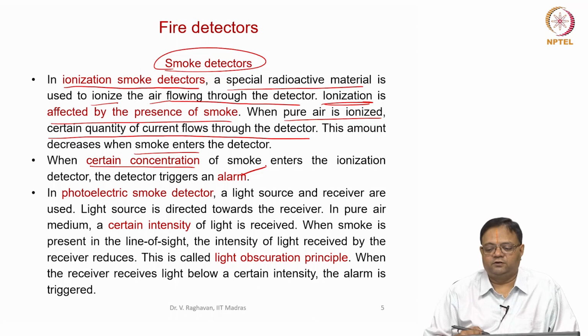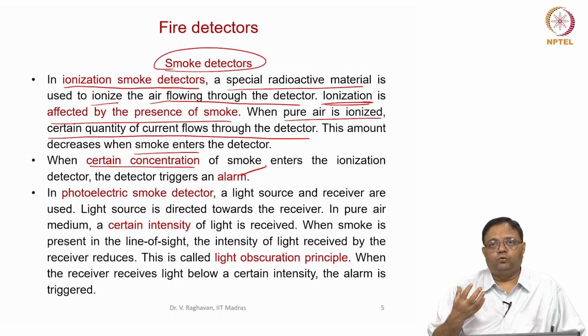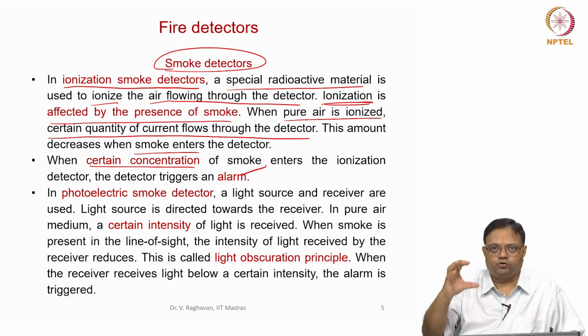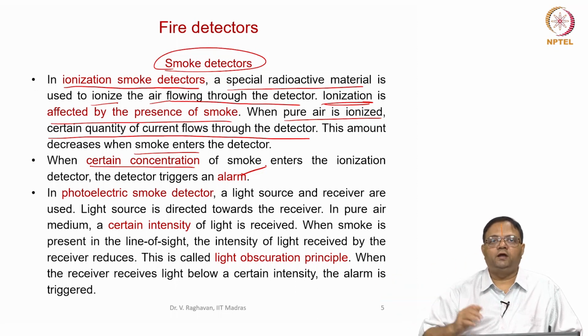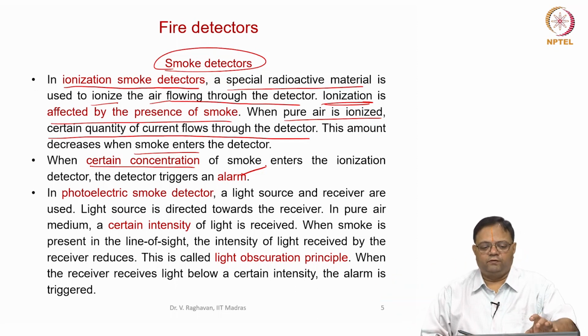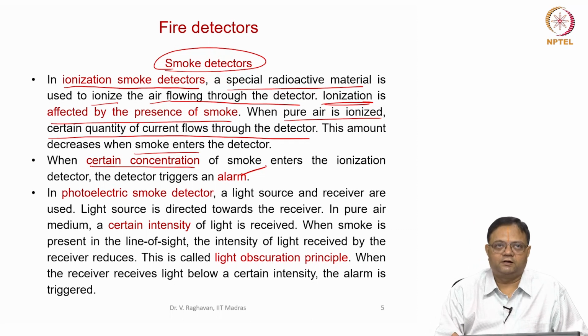Again, calibration is required. You have to generate smoke of different intensities and see what the threshold value is which will cause an alarm when the smoke passes through the ionization detector. So, it is a very well used detector.